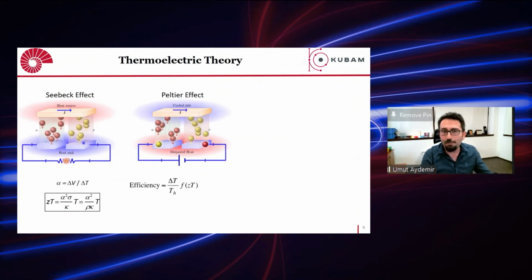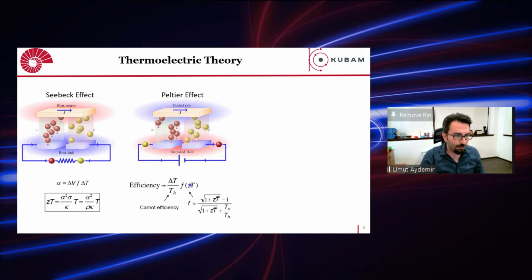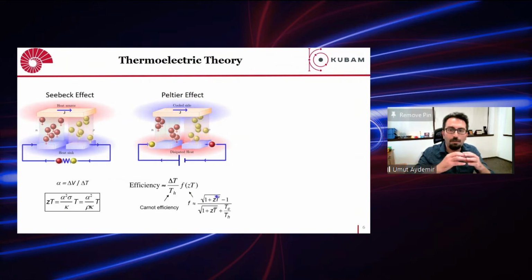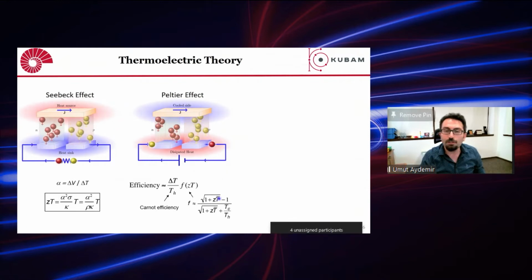It is hard to achieve this high ZT in one material. The device efficiency is related to the Carnot efficiency times a function of this material ZT, but instead of one temperature, we are interested in the broad temperature range, or let's say an average ZT. So for us, the material should show high ZT for a broad temperature range rather than one peak temperature.